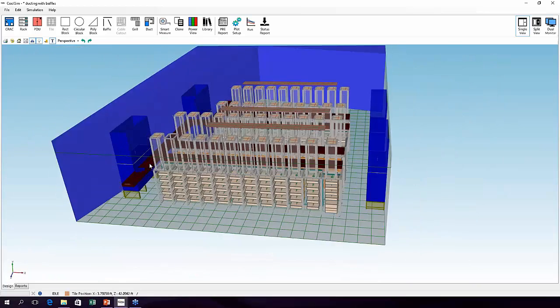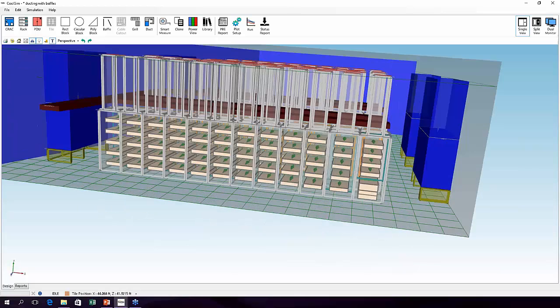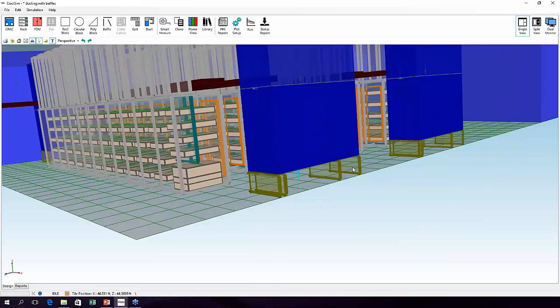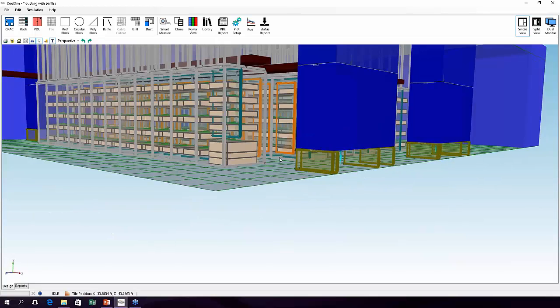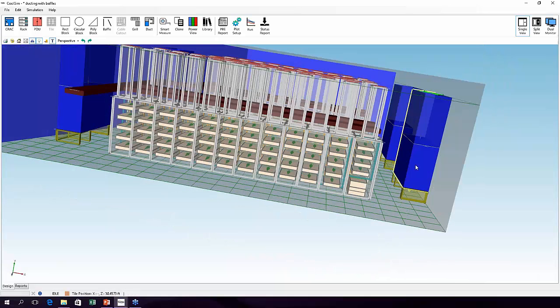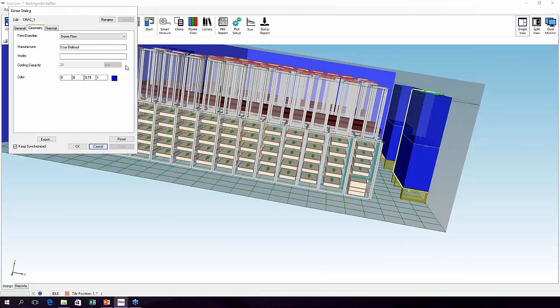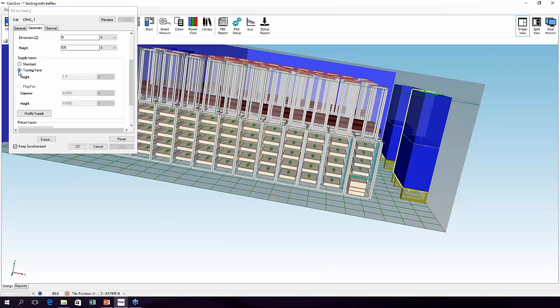They've used extensions on their cooling units. They did build, it appears, these structures underneath, which are not really necessary because you can use the turning vane, which is just a function in the editor. So you can turn a turning vane on under geometry, and you don't need to build those uniquely. So turning vane is right here. They could have put a turning vane on, and there it is. It needs to point the right way, by the way.